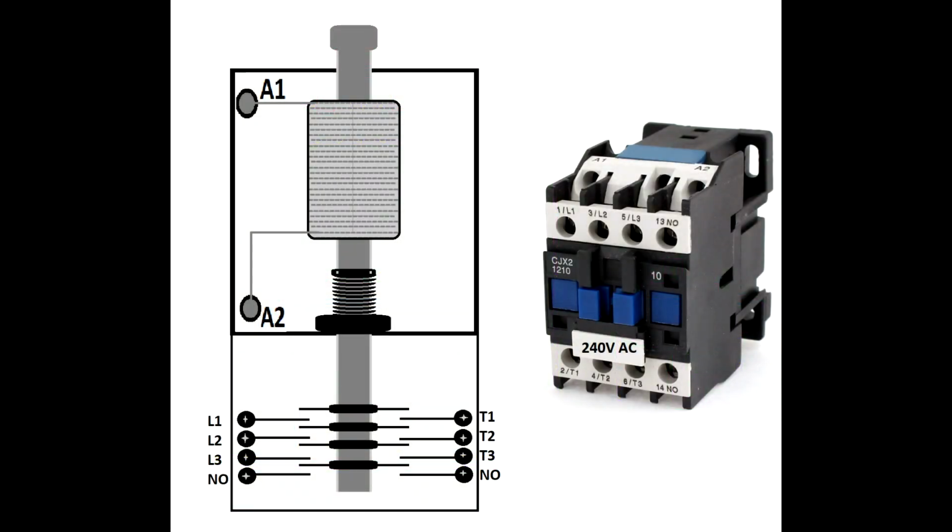By the way, I have a video in which I explain how the contactor works. Guys, if you understand the difference between a control circuit and a power circuit, you'll be capable to investigate the boiler printed circuit boards. The contactor shouldn't be big like this. There are some small relays, but they mostly work on the same principle, unless they are SSRs, which means solid state relays. I'm going to speak about this in another video, but if you look through my other videos, I already explained how the contactor works, and if you want to integrate this on thermostats or a programmable logic controller or building management control, just watch my video and understand how to wire this into the building management control.